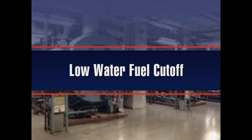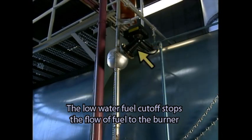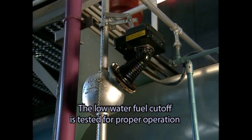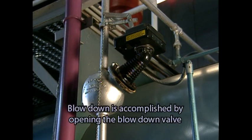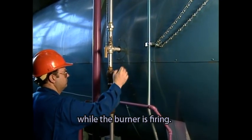Low water fuel cutoff. The low water fuel cutoff stops the flow of fuel to the burner in the event of a low water condition. The low water fuel cutoff is tested for proper operation by a blowdown when taking over a shift. Blowdown is accomplished by opening the blowdown valve while the burner is firing.